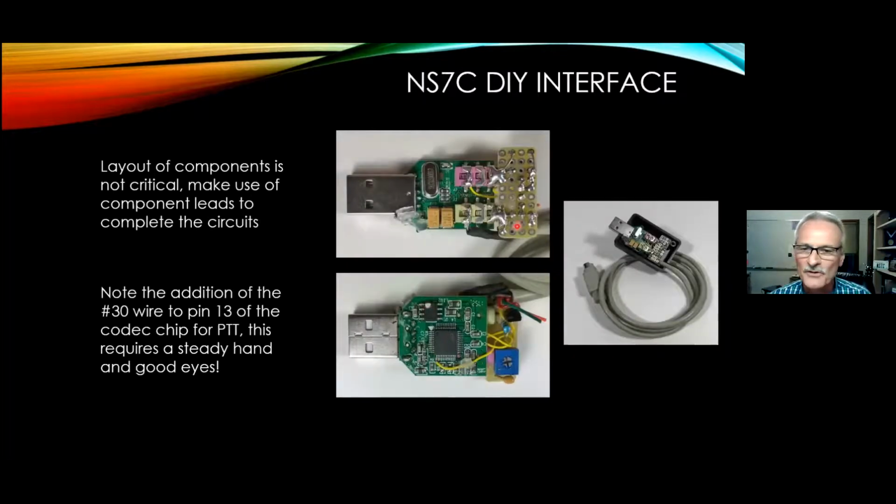Okay, so here's what the circuit looks like. I took a piece of perf board. I actually took my Dremel and ground out the other side, you can't see it on this side, so it fit the curve of these connectors right here. So it lays right up flush against the top of the connector, and then I just flowed some solder across onto the board here. That's not only my ground connection, but also my mounting of the circuit board. And on the other side of the board, I've got the transistor here for push to talk. I've got the resistor feeding that transistor.